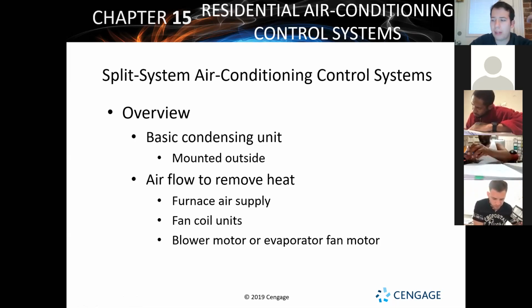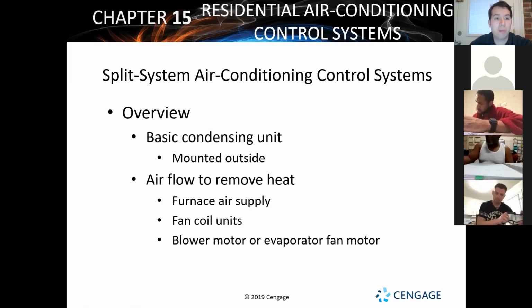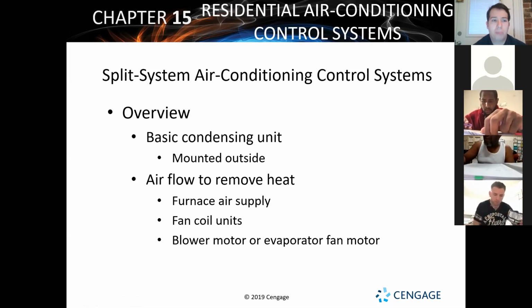The only thing that's really different between either of the 2 is making sure that you've got proper airflow in both is key and important. It's one of the most common problems that can happen with the system is improper airflow. Either the condenser coil outside has got a blockage because it's built up too much dirt and debris, it's pulled in too much crap across it over time, or a filter's dirty, or the ductwork is all clogged up with dirt and dust and debris. And you've got to have that proper airflow.